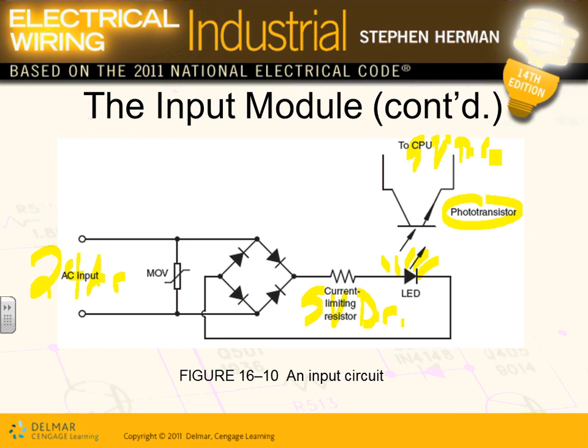One more time: you bring the 24 volt signal, you convert it into DC, and put it through that circuit. The circuit will power an LED light. The LED light will be sensed by a phototransistor, and the phototransistor will convert this into a signal that comes inside the CPU as 5 volt, which converts into the digital number one, meaning we got an input to do something. Any comments, gentlemen? Any questions about this? This is probably the heart of how the input module works.